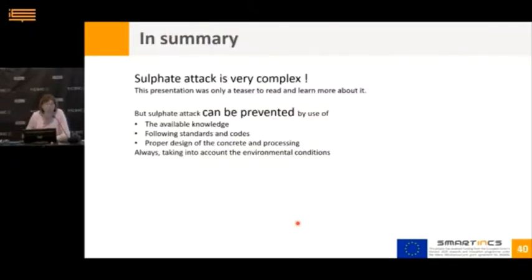So just to conclude, sulfate attack is very complex, and this presentation could not cover everything, but I hope you learned something about it. We also have seen that we can prevent sulfate attack by just following carefully what standards and codes prescribe us, by taking into account the knowledge that we already have, and by just the proper design of the concrete mixes and the curing and processing. So this, of course, always taking into account the environmental conditions that you will be facing over the service life of your concrete element.